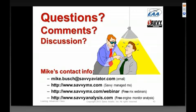Well, first of all, in terms of the red box and red fin, we want to keep all of the CHTs out of the red box, out of the red fin, so the one that will dominate our leaning decisions will be whichever one is the hottest. Now, if there are big differences between different cylinder head temperatures, there are 2 possible reasons for that.